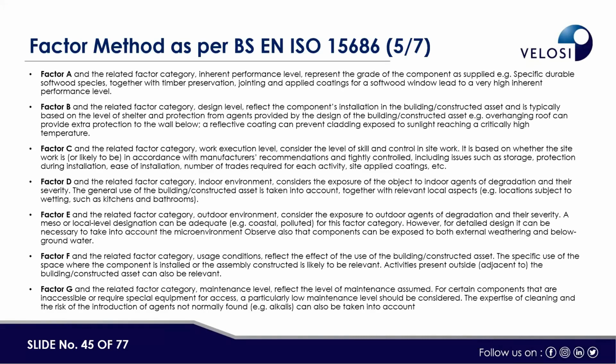Then factor E is for the outdoor environment, like the exposure to outdoor agents and the severity of degradation. Local level designations can be adequate, like coastal or polluted, for this factor category. Factor F is for the usage condition, which reflects the effect of the use of the building or constructed asset.